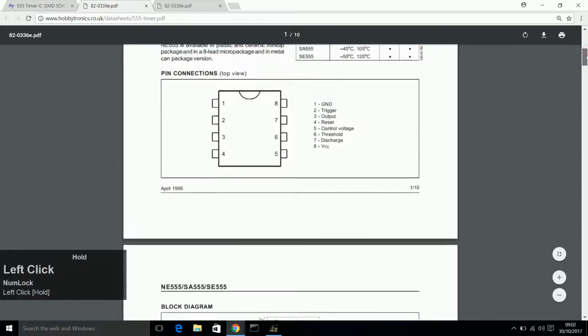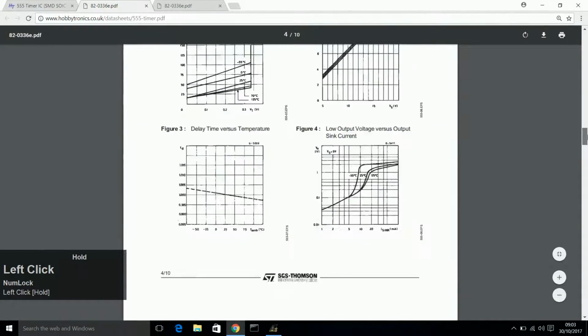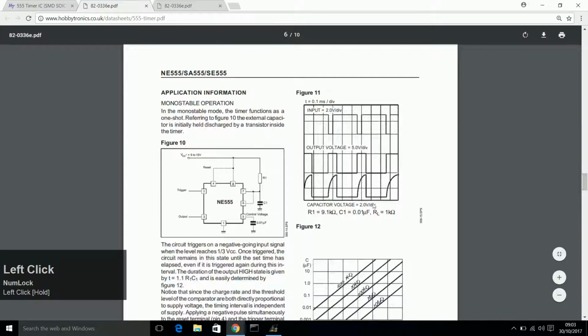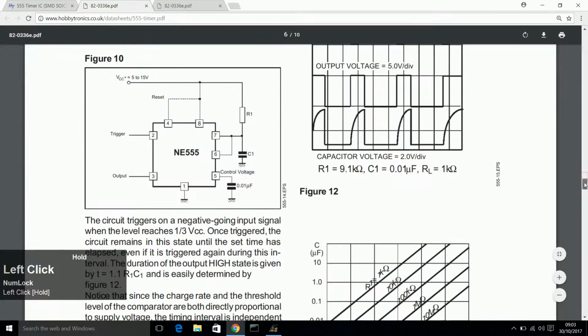If we look through this datasheet, we can see that they have actually provided us with a recommended layout for a schematic view. It's over here. So we have ground at the bottom, VCC at the top, and the other pins are scattered accordingly, but you can see that they're not in order. 1, 3, 5, 6, 7, 8, 4 and 2.